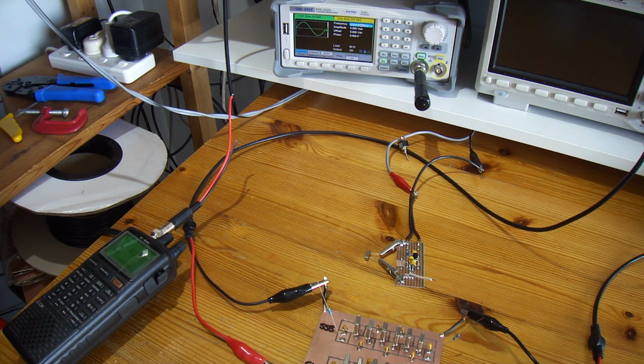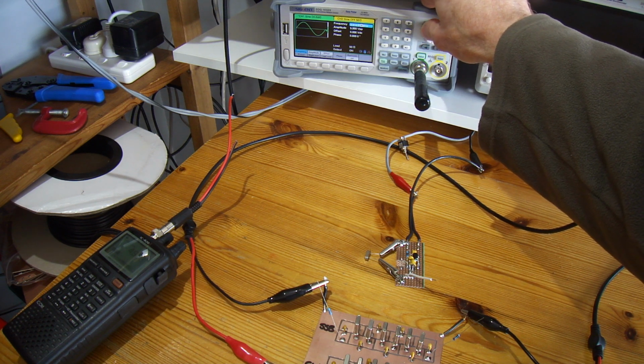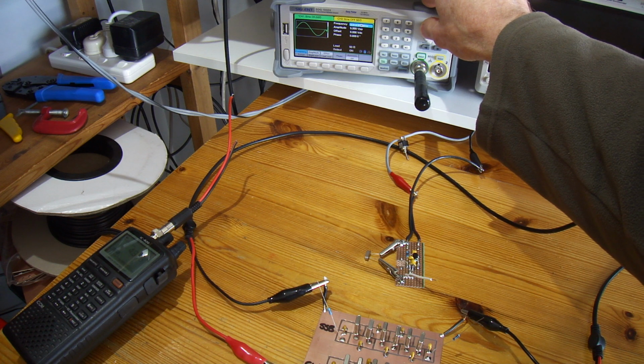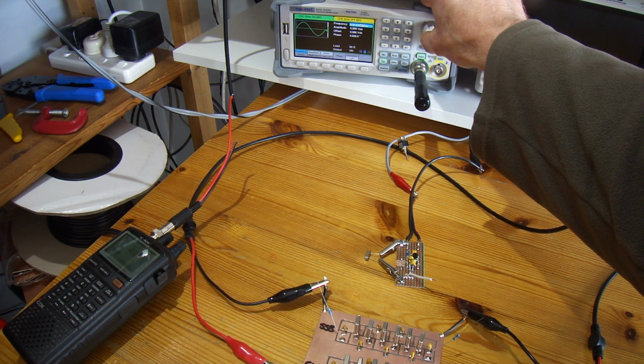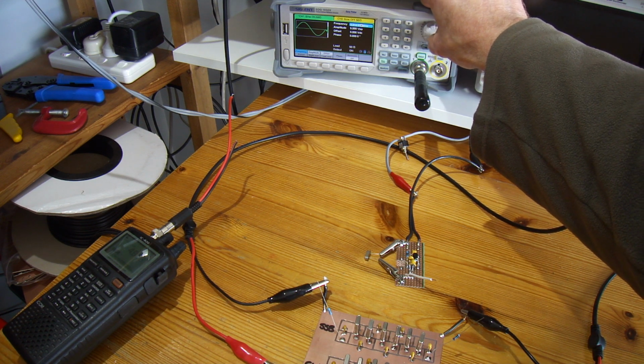So that there is a single tone that's picking up both the SIG-gen and the crystal oscillator. Now if I was just to tune slightly off, you'll hear that beat coming in. That's slightly high in frequency, coming back down again, back down to 0 beat, and then going below the frequency. And the further I go, the higher the beat.